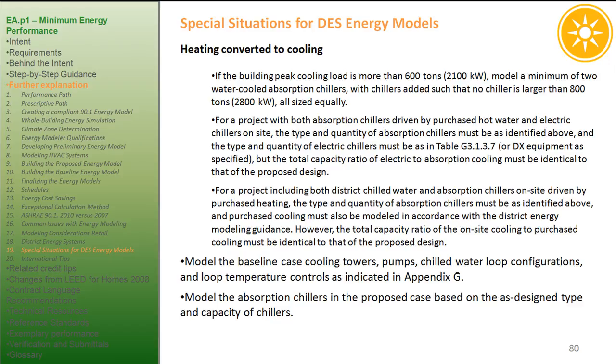Model the baseline case cooling towers, pumps, chilled water loop configurations, and loop temperature controls as indicated in Appendix G. Model the absorption chillers in the proposed case based on the as-designed type and capacity of chillers.